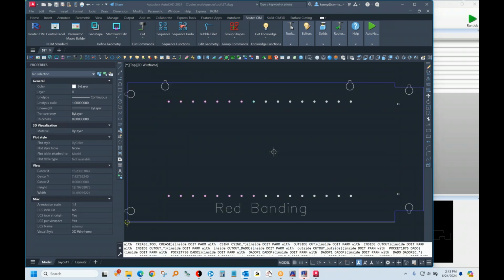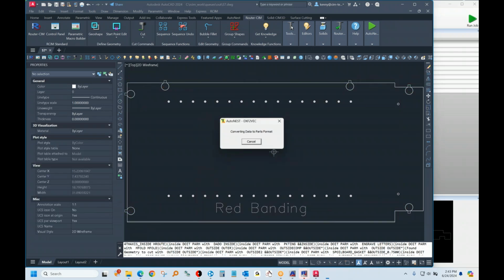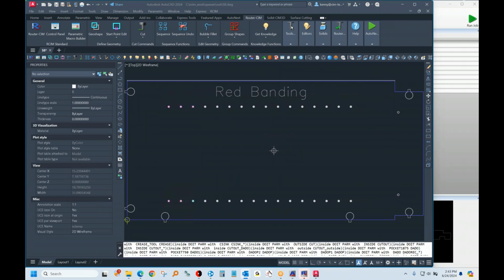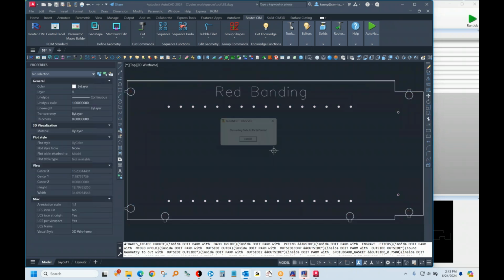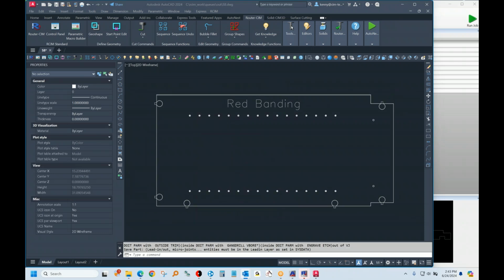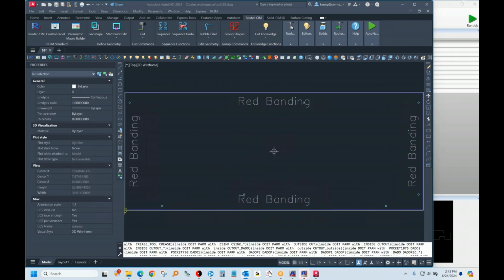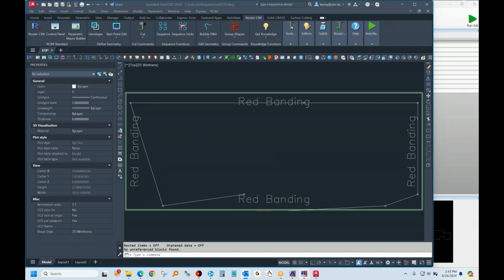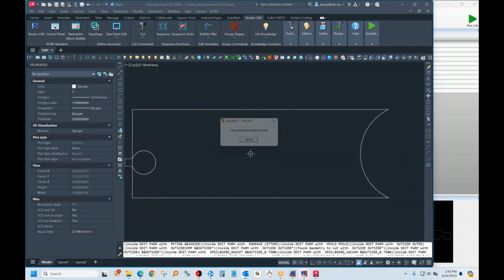So that was all of the Inventor files in a folder, and I dragged and dropped the folder in there. Now, the folder name is going to be the name of the assembly that you want it to process. So that's one of the stipulations there, because you could have a bunch of different assemblies in a folder, and it's going to look at the name of the folder to be the name of the assembly to process. And as you see, the rest is automated.